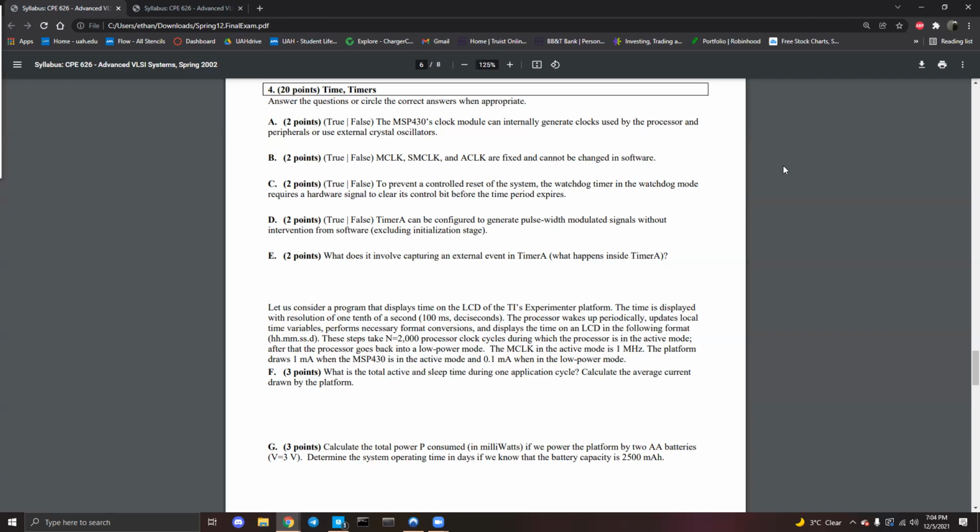You set the total length of your signal with your CCR0 register, and then you can pick any number of registers, like CCR1 through however many there are, CCR6, who knows, right? Those values will all independently generate their own PWM signal when the timer approaches them and generates an interrupt. But the thing is, you can also do it in hardware.